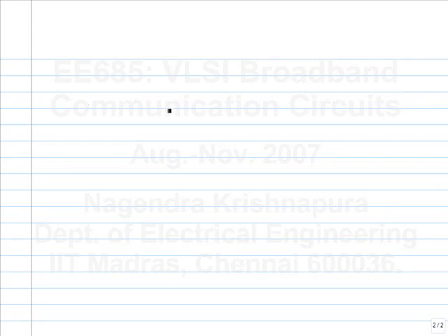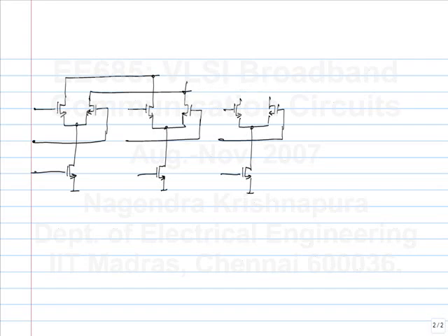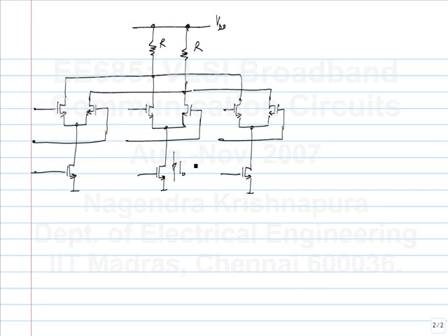Let's assume a 3-tap equalizer with one precursor tap and one postcursor tap. Okay. Then I'll have 3 differential pairs in parallel. So let's go and design this in a complete way. So let's say this is terminated by load resistances R and R. Let's say the middle has a tail current I naught, and the equalizer I want to realize has weights G minus 1, G0 and G1.